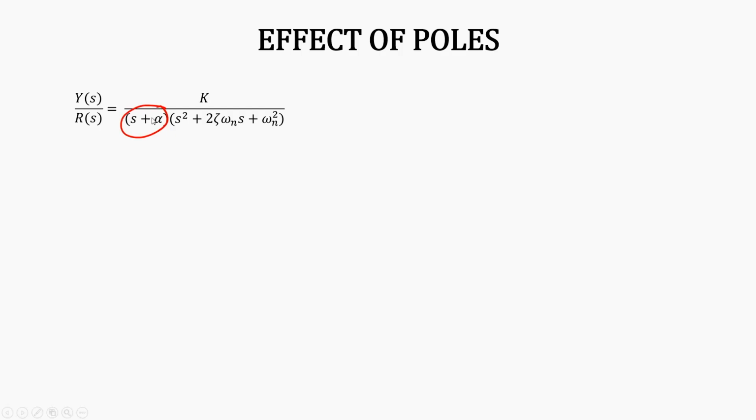That is why the specifications have been made in such a way that they are not affected by just scaling the transfer function. Now, let us look into the case when we have additional poles or additional zeros in the system. There is no guarantee that you will always get a second order system. It may be a third order system, it may be a second order system with zeros in it. So, let us see what happens if we add an extra pole into the system.